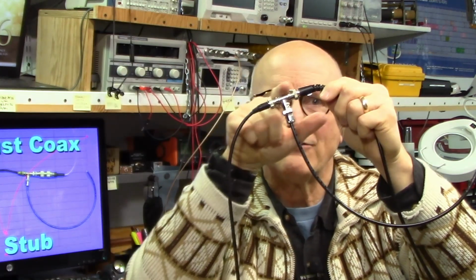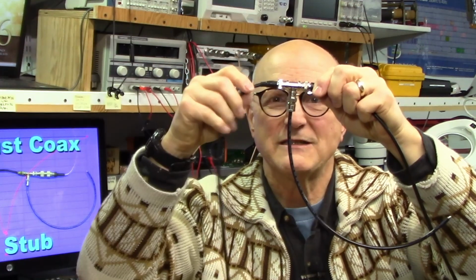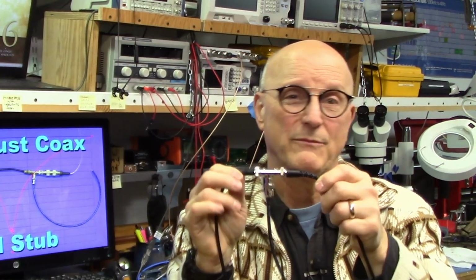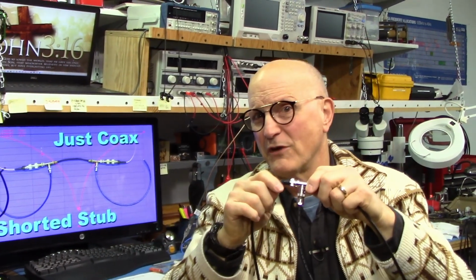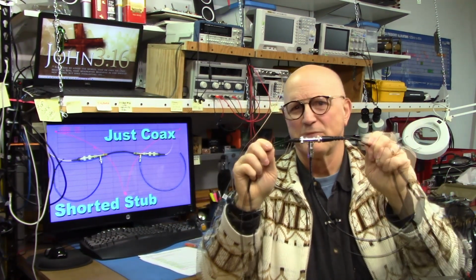Any signal traveling down that feed line at that frequency will be shorted out at the T by this coaxial stub. We now have a band reject filter at the frequency in question. Now my bench experiments show an attenuation around 30 to 40 dB doing just this. But you know, we can do even better than this. Suppose we want more than 30 to 40 dB of attenuation. How do we do that?